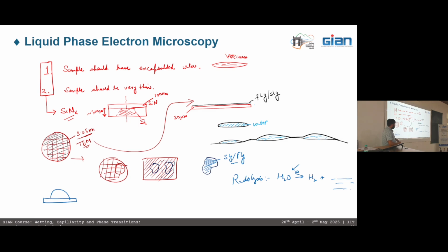And in the end, when you sandwich 2 grids, it might happen that they are not aligned very well, and the TEM holders which we have, where this sample goes, have exactly a 0.3 mm slot. If these 2 grids are not aligned with each other, then they will not be able to fit into this. So that is another thing you have to take care of when you prepare this sample, right?